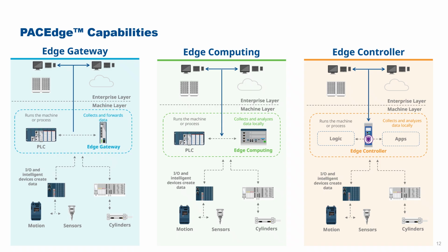So for example, if you're running a digital twin and you see that your process is drifting away from ideal operating parameters, then what the edge computer might do is, as part of the digital twin it's running, it might tweak the set points in the PLC to bring the process back into control, or to minimize any sudden downtime events or any unexpected operation of the plant or machinery. So we're doing more complex control here, and this is why we need the edge computer.